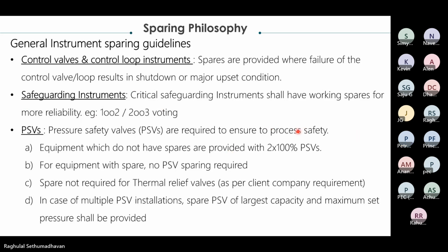Then PSVs. Equipment which do not have a spare will anyway be provided with 2 into 100% PSVs as a minimum. For equipment with a spare, a spare PSV won't be required because we can either take the equipment out or change over. Spare will not be required for thermal relief valves. It also varies from time to time. In case of multiple PSVs, the spare is of larger capacity and maximum set pressure available.